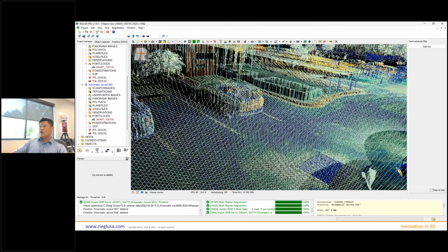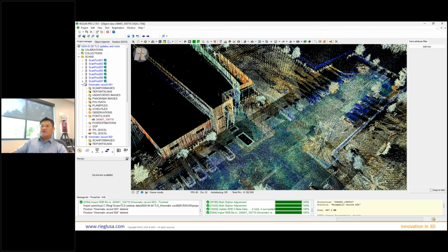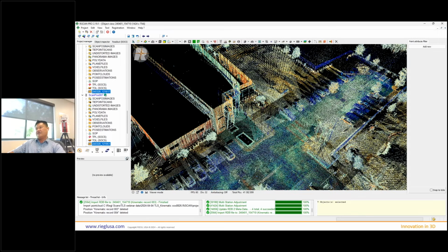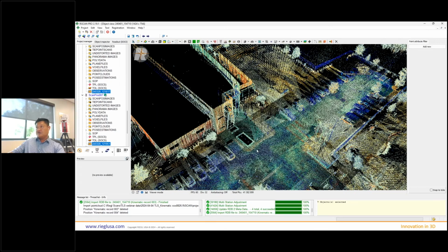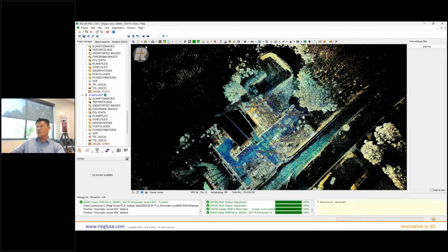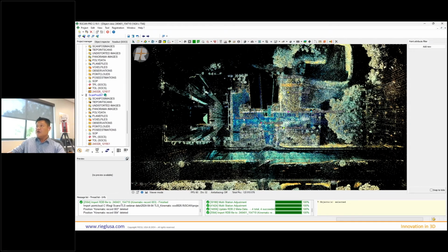But where does that line up with our threshold data, right? Don't forget, our threshold data is on survey control, so our threshold data is fixed. Bring these guys in. I'll make that just different colors. Now, let me do a cross section to see.